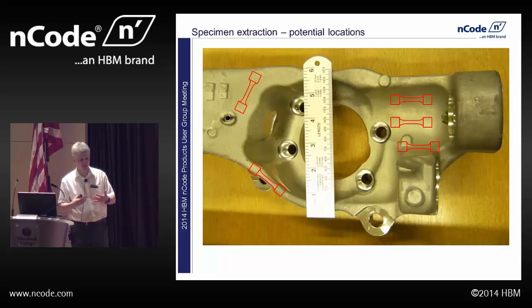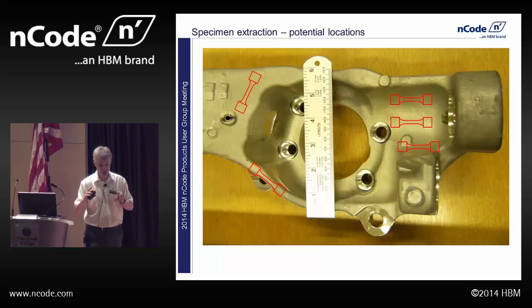So you've got to step back from that sometimes and then generate the samples to give you the same material, composition, surface finish, and microstructures you would get in the final component. So you've got to be a bit careful about how you generate the material itself that you use in the test specimens.